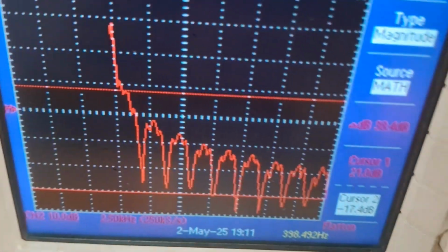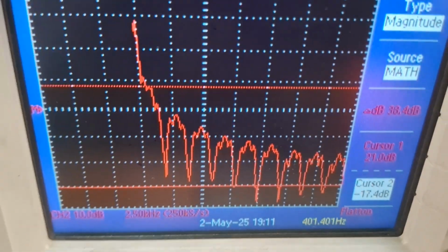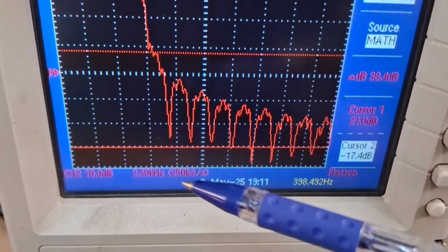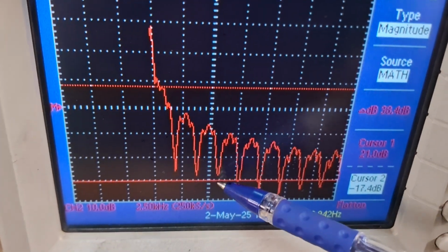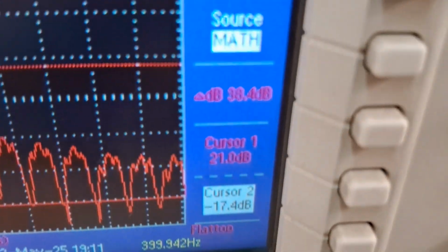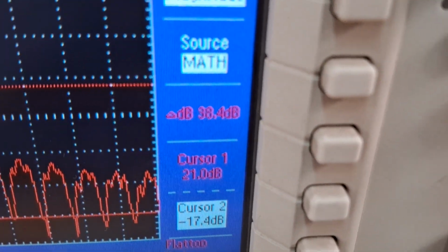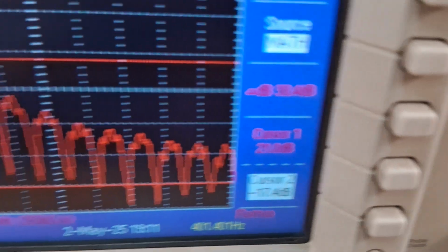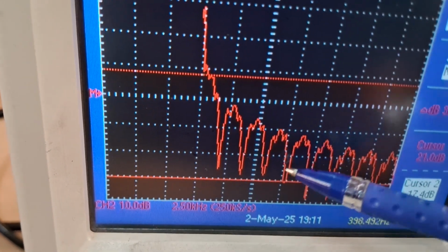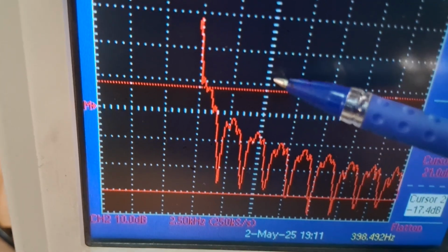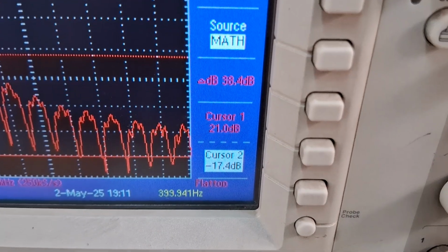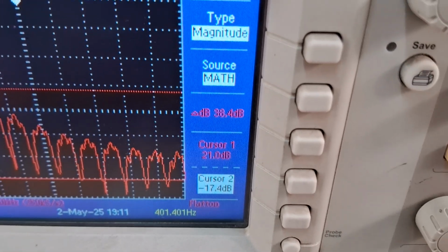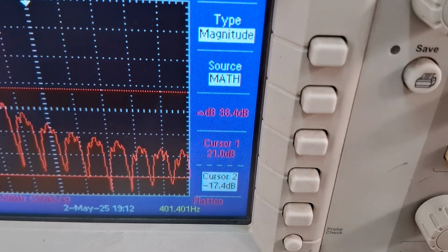Now this is a manual measurement which you can do. Once you are placing the cursor, this manual cursor is arbitrary, wherever you can place it, and as per this reference you are now measuring the dB value. What is the dB value for a cursor that you are measuring? So now here I am taking the delta difference, because I have placed one cursor below here and the first cursor is over here. So the first dB value which I have to measure is the delta difference. So what is the delta difference? It is something corresponding to 38 dB something, right?